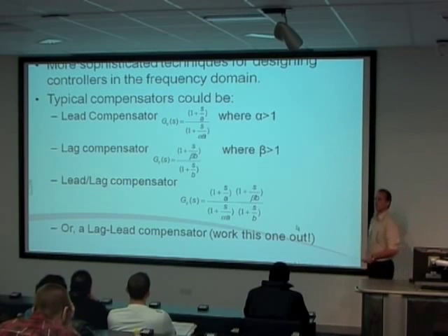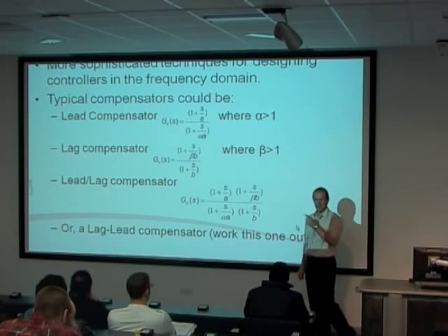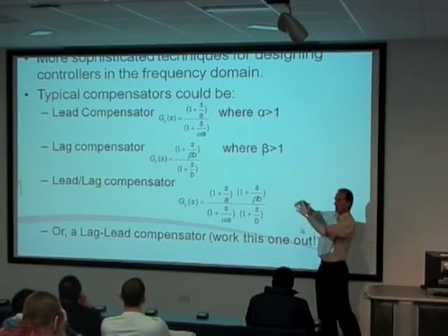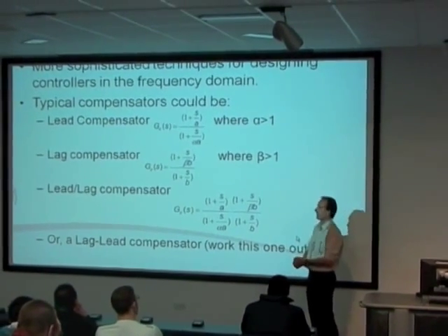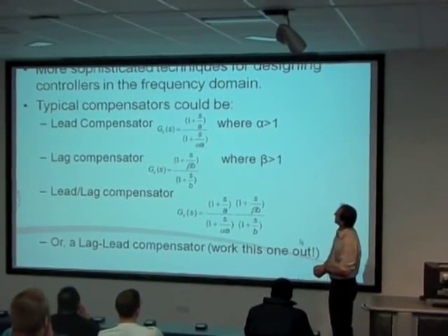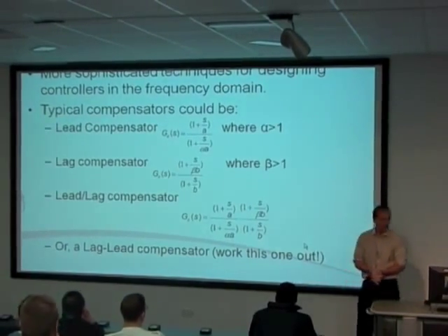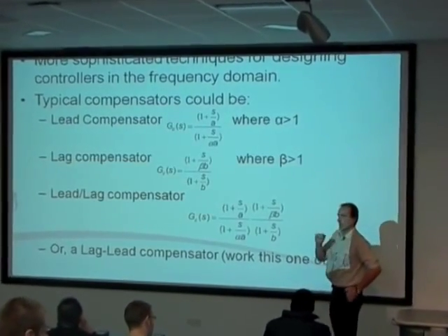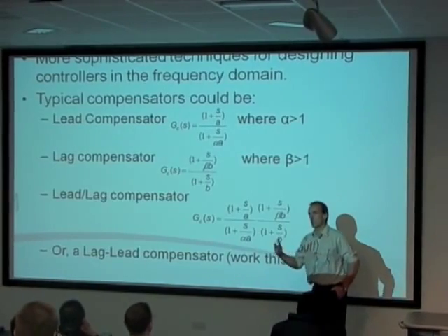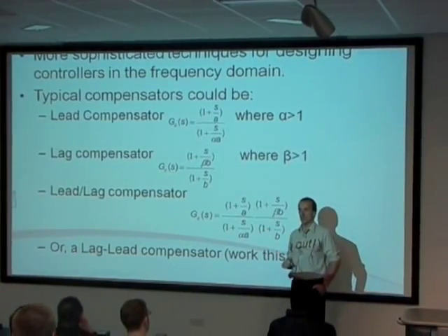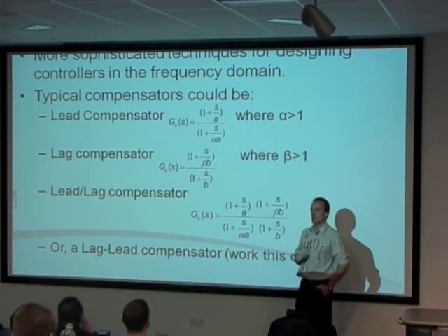That's the easy one. What else can we do? Well, we can get a bit more sophisticated with all this stuff. And instead of just crudely lifting one of the curves up or dropping it down, we can introduce more sophisticated techniques in the shape of what we call compensators. These are devices that you put in just the same way as we would that gain. Just put them in the forward path so they appear in the open loop transfer function.